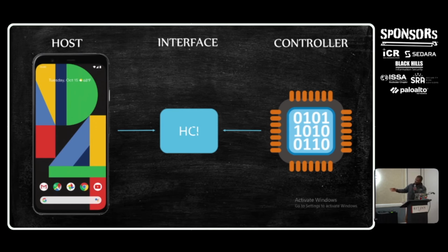The reason why I bring this up is that if you're trying to do Bluetooth reverse engineering, because of the difficulty in actually doing practical Bluetooth sniffing, it's important to get the information before it's being broadcast, because you run into 2 issues. Broadcast Bluetooth data can be encrypted, and it's not going to be of much use there. And also, there's a lot of diagnostic information that's sent from the host to the controller that never makes it over the air, like instructions for setting a long-term or short-term key.